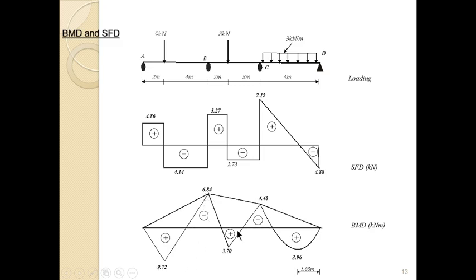We come here, we do a similar thing. Remember this simply supported diagram was 9.6. So we now come here. This is 6.84. This is 4.48. But at 2 meters, which is not midspan, we use similar triangles to find the distance from here to here. When you subtract it from 9.6, this is how you will have this place. So what we now have is here.